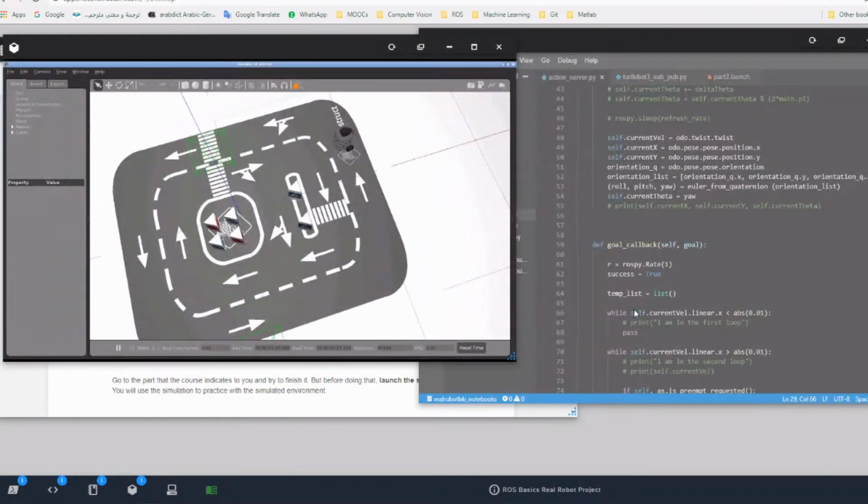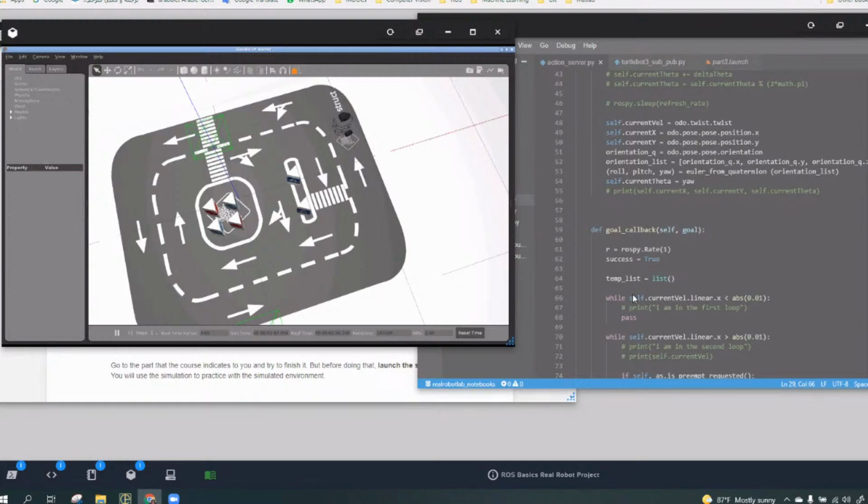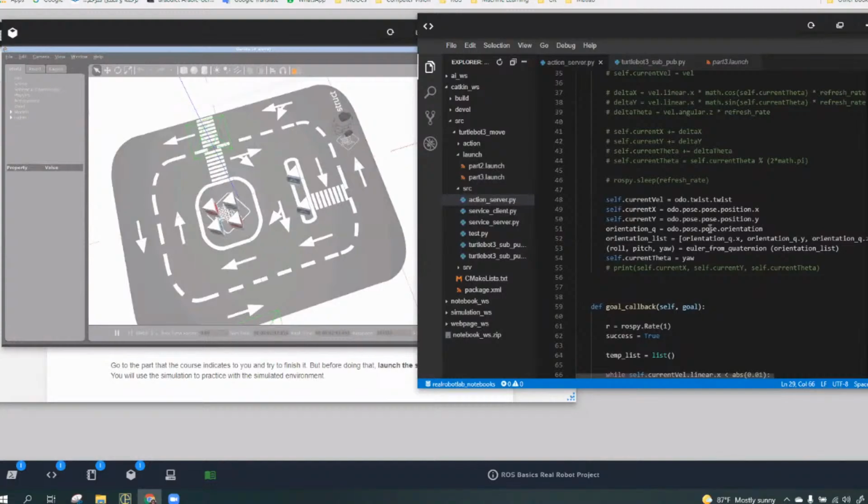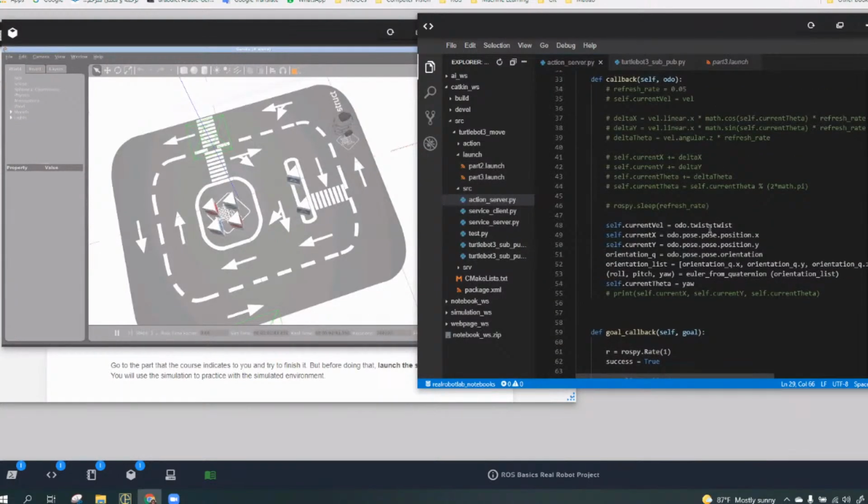So let me ask you, because this actually relates to what we saw in the presentation before. In your action server for recording how the robot moved, you have a commented section, and you've told me about this, but I think it would be interesting because I thought it was a great solution on your part. Instead of the odometry topic, it's using the cmd_vel topic. So can you explain a little bit why you did that and how you thought about solving it?